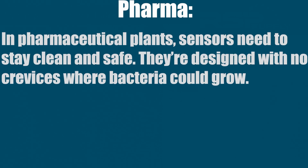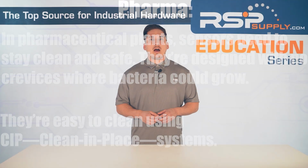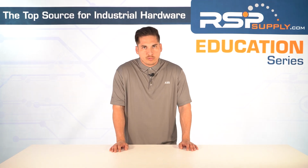In pharma, you're going to see sanitary sensors. In pharmaceutical plants, sensors need to stay clean and safe. They're designed with no crevices where bacteria could grow. They're easy to clean using CIP, or clean-in-place, systems. And 3A compliance ensures they meet strict food and drug safety rules.